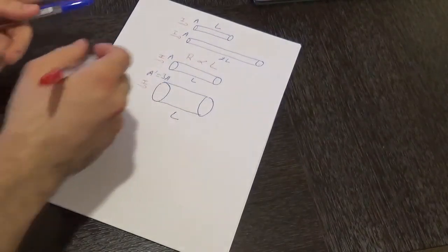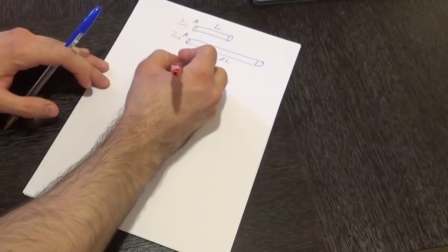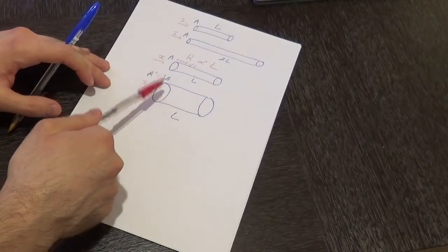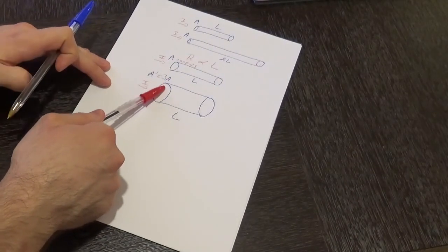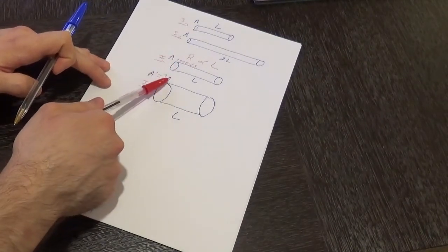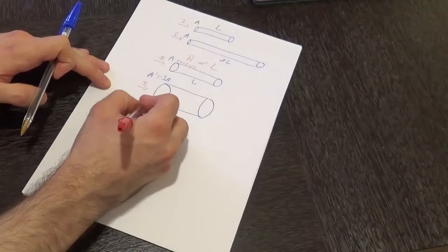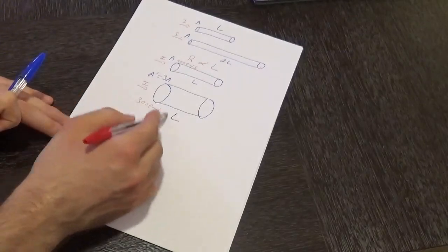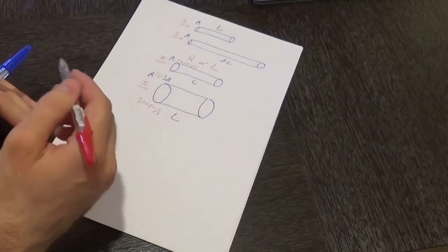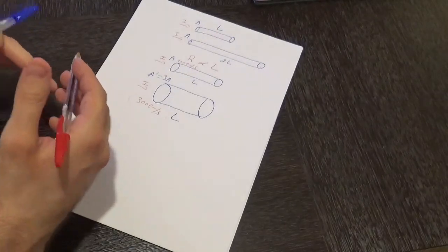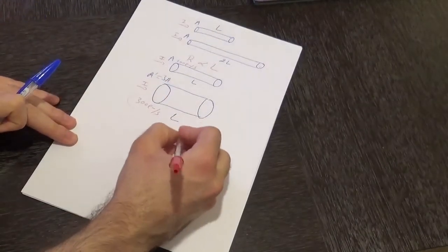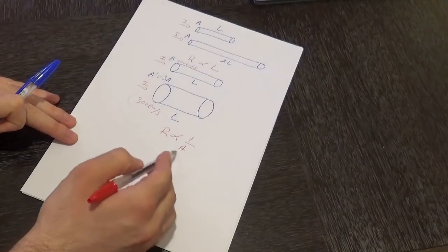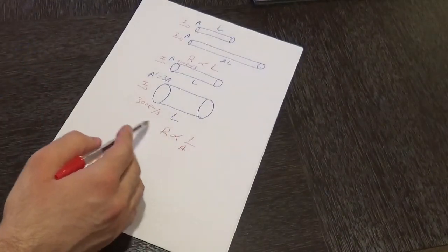So for example, let's say that first conductor is allowing 100 electrons per second to flow through it, whereas that second conductor, which has 3 times the diameter of the first one, or 3 times the area of the first one, is going to allow on average at least 300 electrons per second to flow into it. So that incremental number of charges is going to have a counter effect on the resistance of that conductor. So basically it's going to decrease it. Therefore the resistance is basically proportional to the inverse of the area. Whenever you increase the area of a conductor, its resistance is going to decrease.